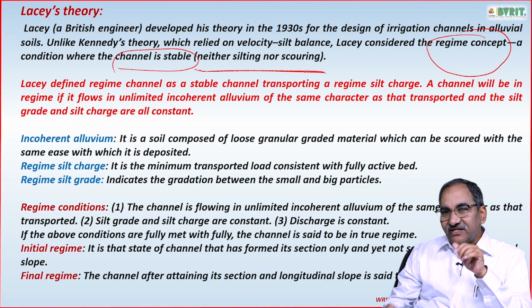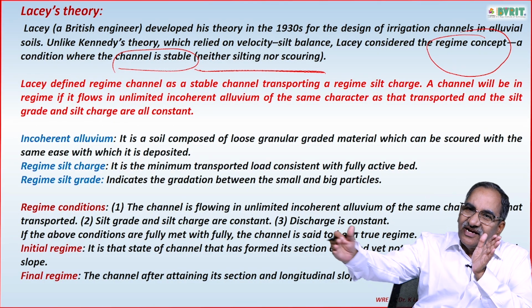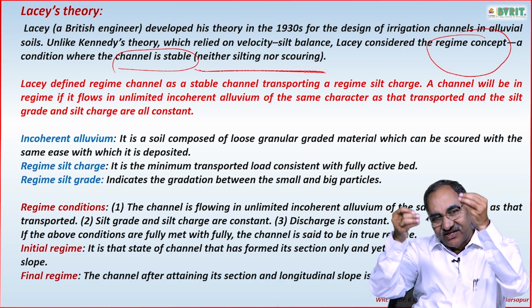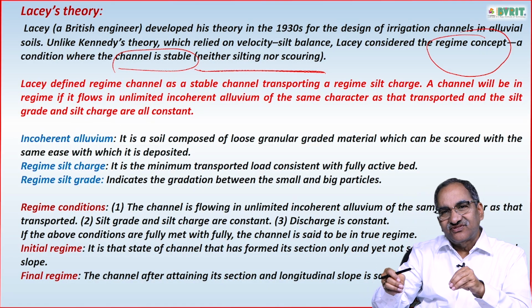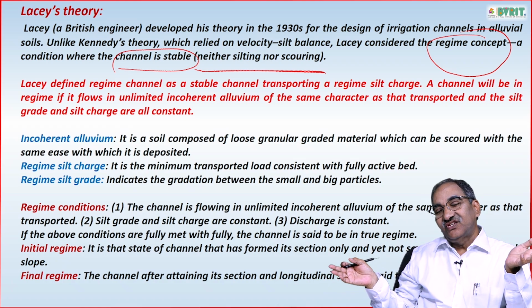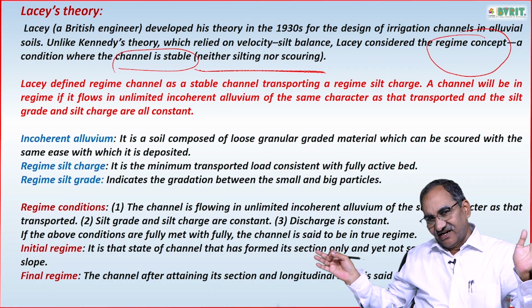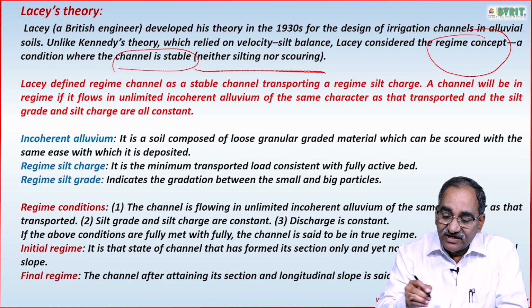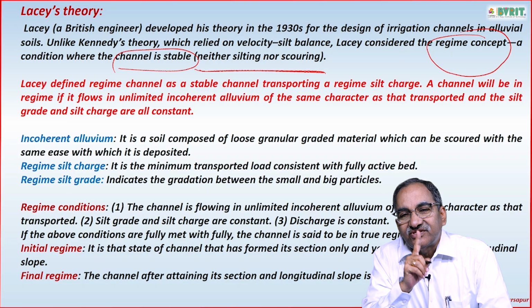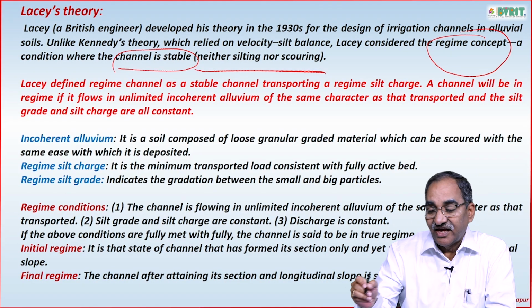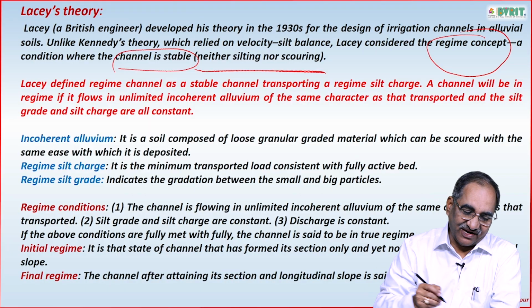Non-silting means the silt is transported along with the water in the canal and is not deposited. Non-scouring means the velocity is not so high that it erodes the bed and the banks. For this non-silting, non-scouring condition, he has given the regime concept.